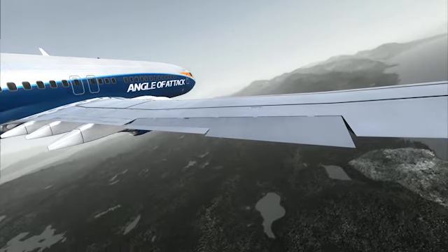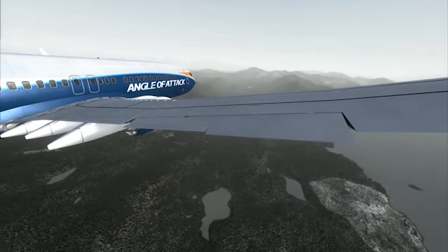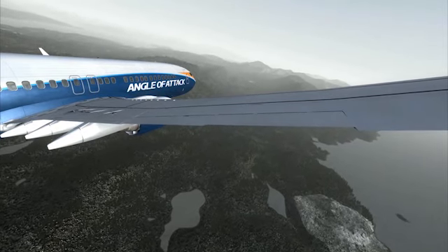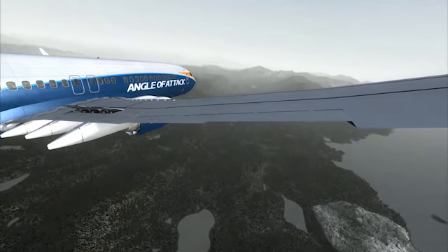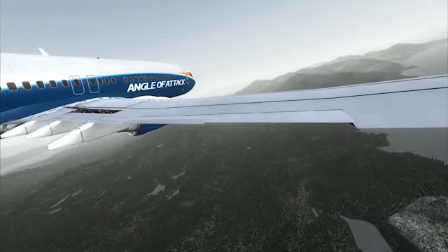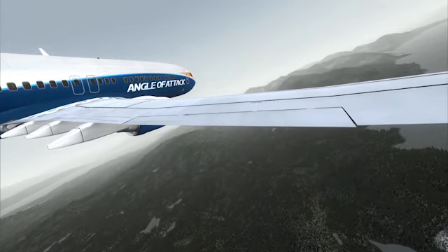This induces a noticeably higher angle of attack in the right wing when compared to the left wing, thus causing the right wing to go up and roll the aircraft towards the left. The ailerons also have balance panels and weights in order to decrease the force necessary to move them during flight.